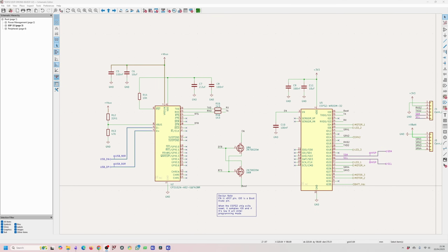Now the BOM is essential for ordering the parts you'll need to build your PCB, or if you're doing a turnkey assembly, then you need to provide the BOM to the PCB manufacturer. So you need to make sure you get this right. A well-organized BOM will save you time and prevent errors when you're ordering your components. It's also useful for documentation and for anyone else who might need to understand or reproduce your circuit.